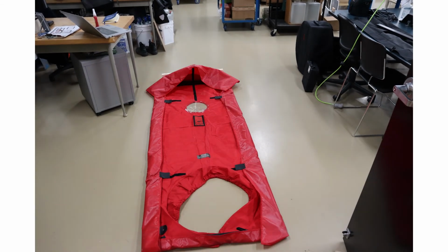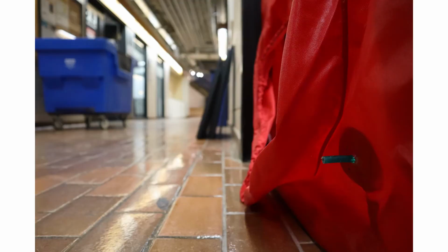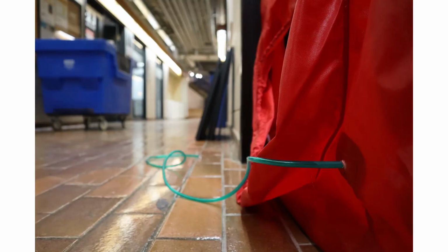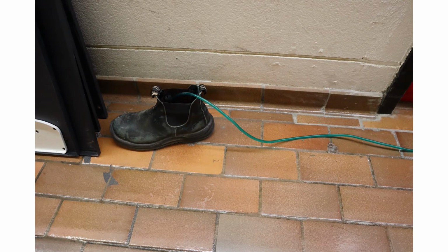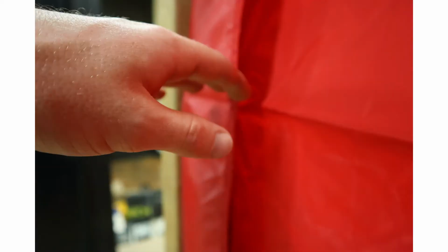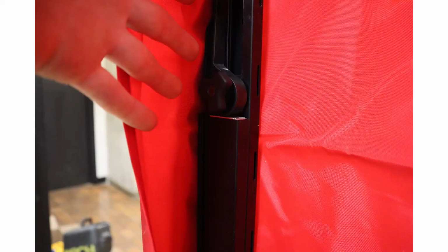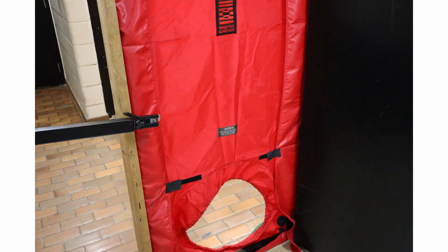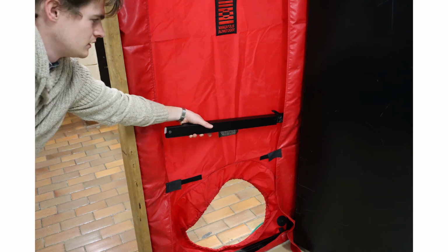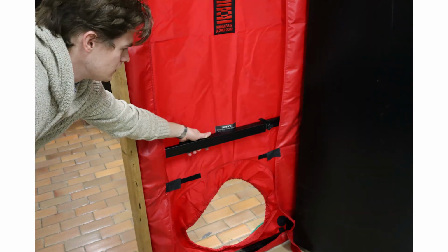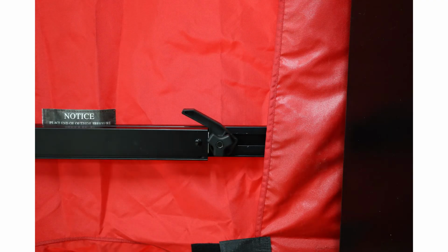Pass the green and blue tubes through the small holes at the bottom of the door panel. Place the tubes in a mailbox or a shoe to keep the tube out of the wind. Place the frame back into the door and lock it in place using the cams or latches. Attach the cross member to make sure the frame stays in place during the test. Ensure that the tubes on the outside are protected from wind gusts, so place it out of the way of the fan. It is helpful to have a second person with you to move the tubes outside, so you do not have to crawl through the fan hole in the membrane.